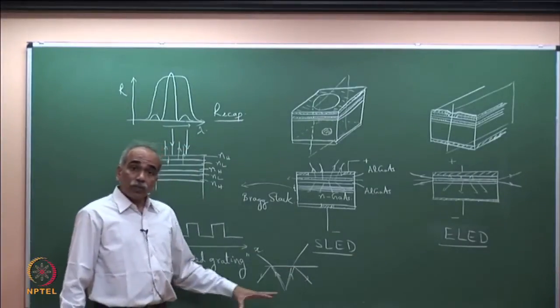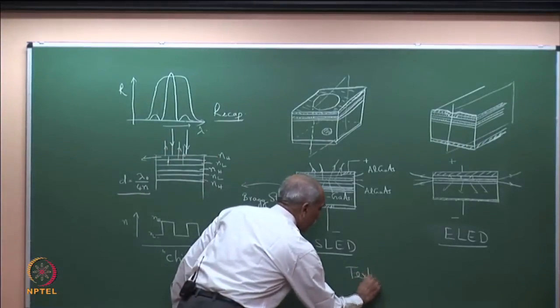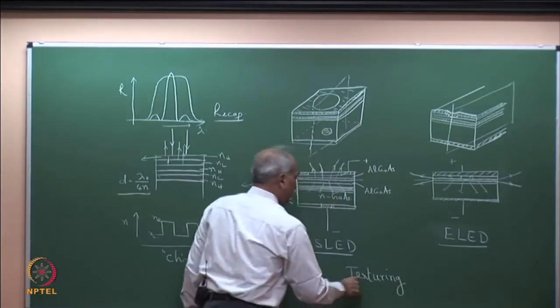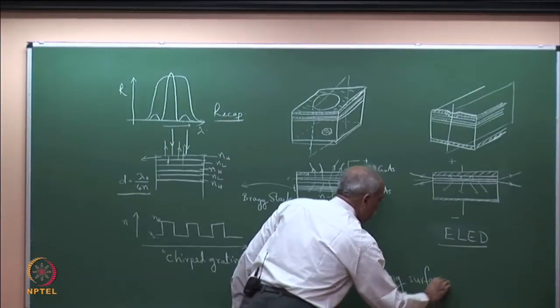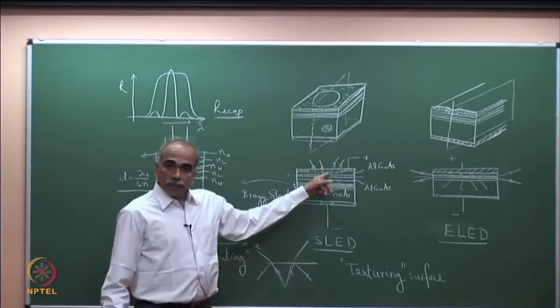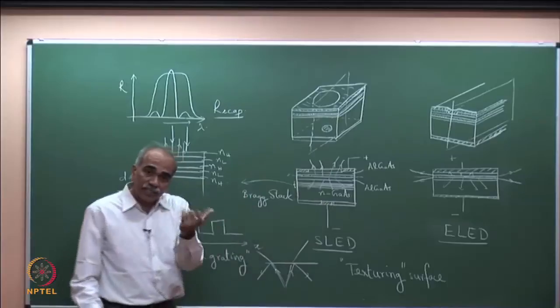There is a technique which is called texturizing. This was discovered much later, texturizing the surface. In surface emitting LEDs, the efficiency can be enhanced by texturizing the surface.